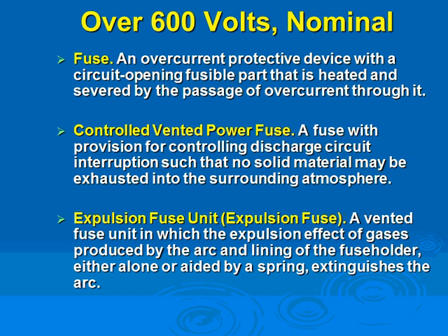When it comes to overcurrent protection devices, guys, the single most important thing design-wise, and I'm not a manufacturer, is how are you going to interrupt this huge energy without burning the surrounding? So they have three technologies. They have air circuit breakers, contacts open in air. That's the cheapest, which we use in the 600 volt or less.